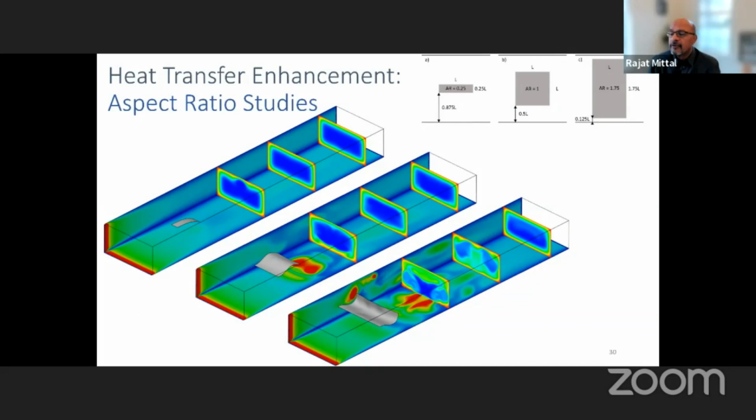People, research groups, have tried all of these different ways of modeling turbulent flows in immersed boundary methods in the presence of moving boundaries. So one would have to go to some of those methods. In our group, we do not do RANS. We solve problems that we can solve using DNS and LES, because that is where the power of our code really shines through.